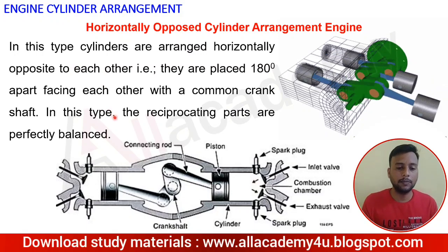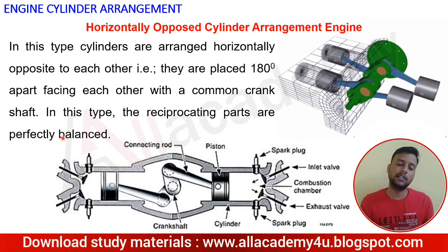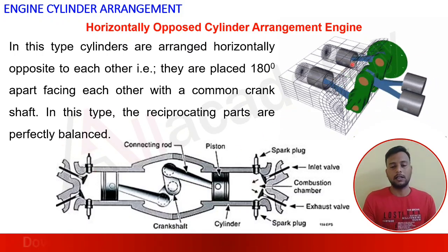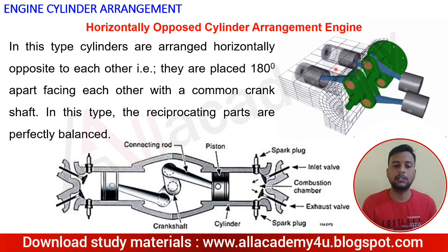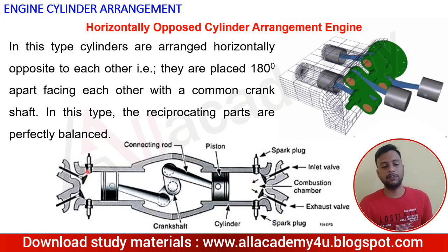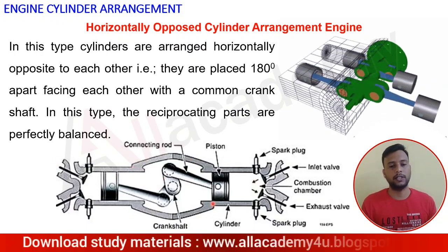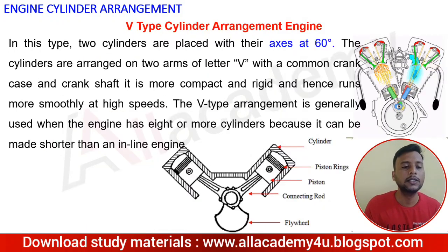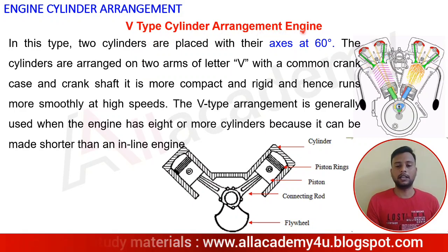In this type, the reciprocating parts are perfectly balanced, whereas in the previous case it is nearly balanced, but here it is perfectly balanced. This animation will help you imagine how the horizontally opposed cylinders work. And in the examination, you need to draw this schematic diagram. Understood? Moving to the next arrangement, that is the V-type cylinder arrangement, or V arrangement.